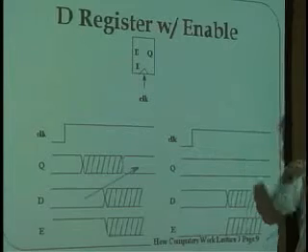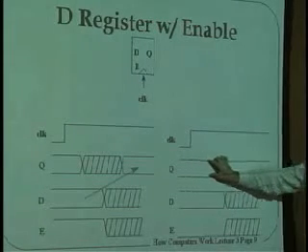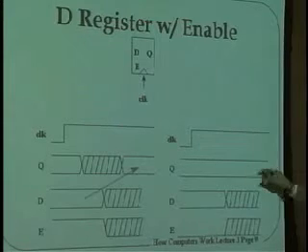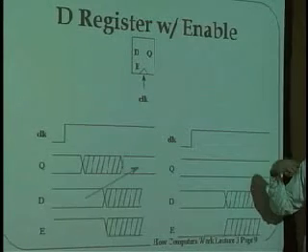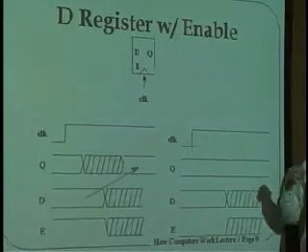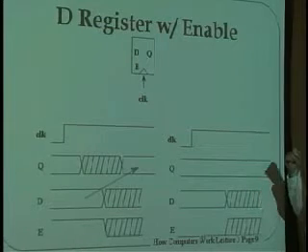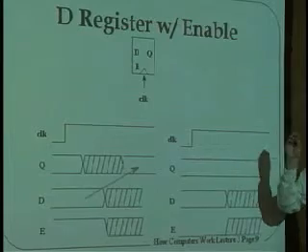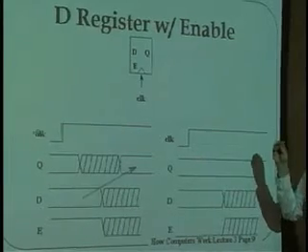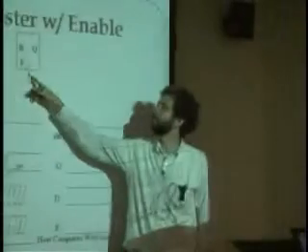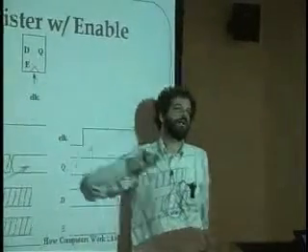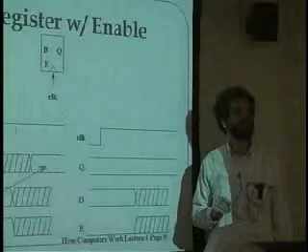It doesn't matter that we pressed the shutter, because Q will just stay with the same value forever and ever, until the next time when the enable is high and we turn the clock from low to high once more. Okay, so it's a mechanism for taking a snapshot of the data on D, propagating it to Q, and the only trick is that whether or not the snapshot actually is taken is predicated on E being high. So that's the enable for the system.